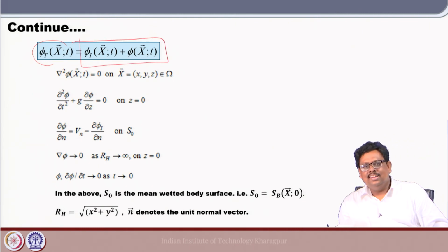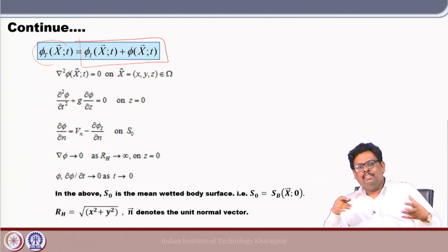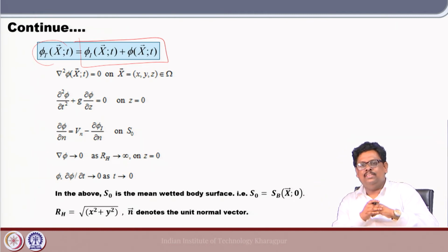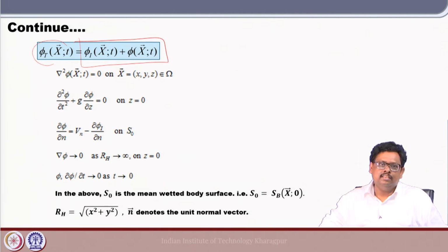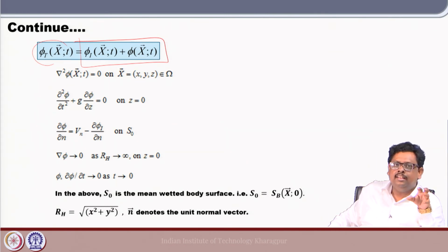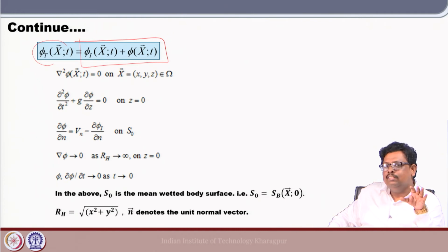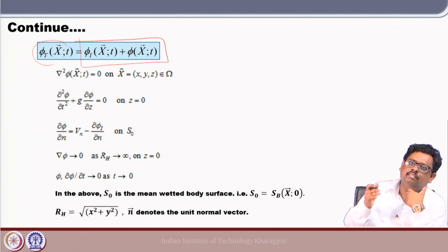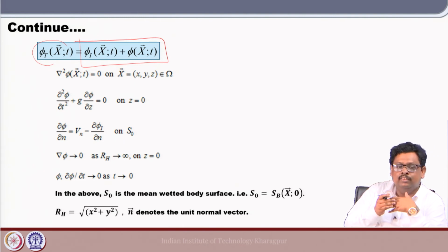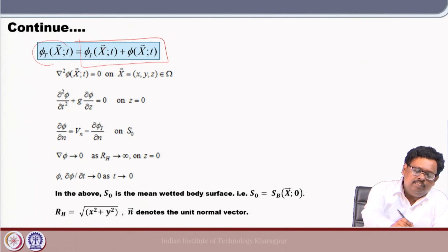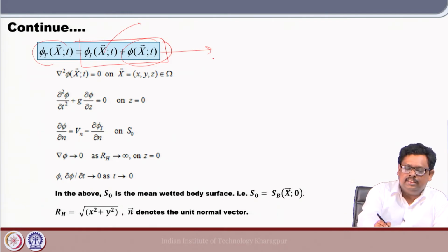Now, in case of a linear problem, if you look at the strip theory, or even the zero speed radiation diffraction problem, we split the phi into phi I plus the rigid body six modes and then diffraction. Here we are simply not using any such further decomposition of the phi. We have only two components: the incident wave potential, and what we can call my disturbed potential.